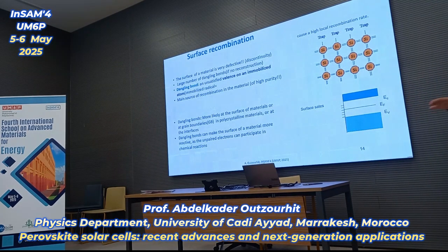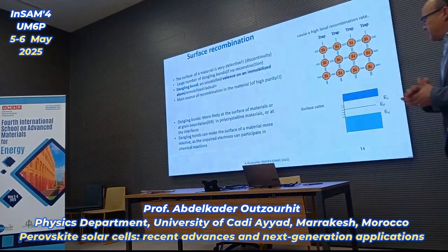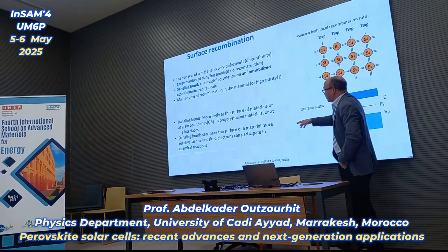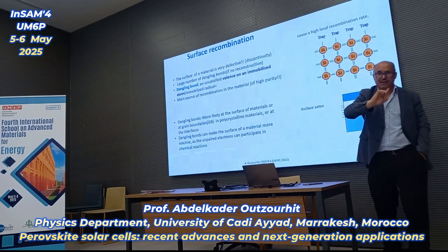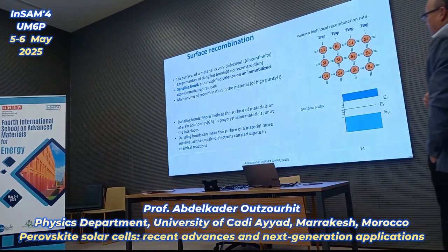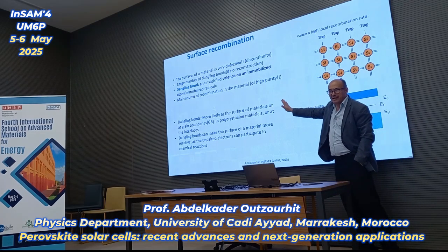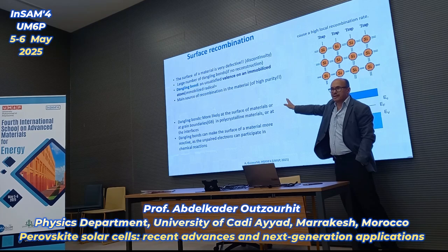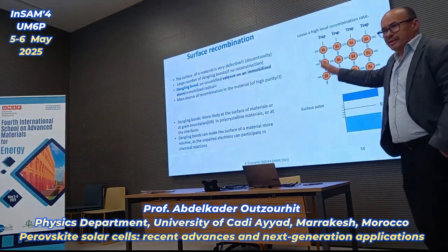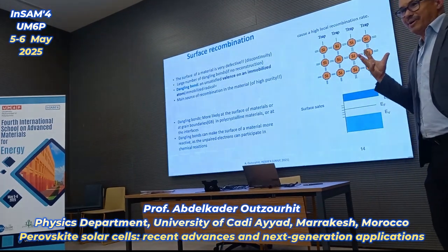And those are killers for efficiency in solar cells, the dangling bonds, because they can be centers of recombination. Okay? And the dangling bonds are also very reactive. The chemists, they know that the radicals react directly with anything. So you see all the work that is going on in solar cells. Even in silicon, they're trying to passivate, or to render these recombination centers inactive, so they don't trap electrons.